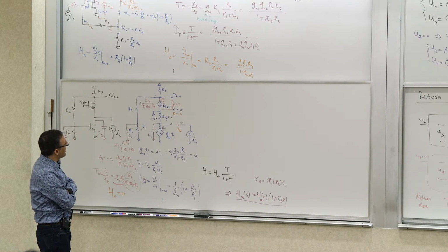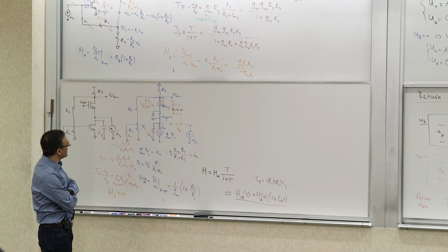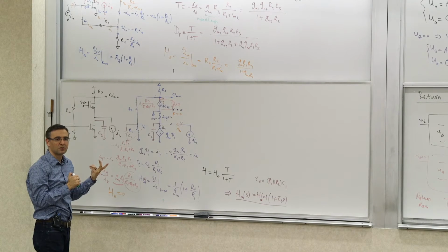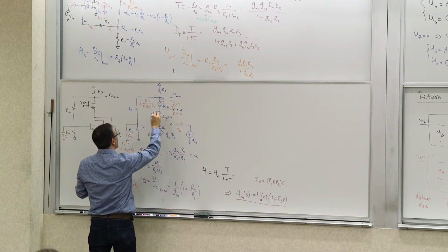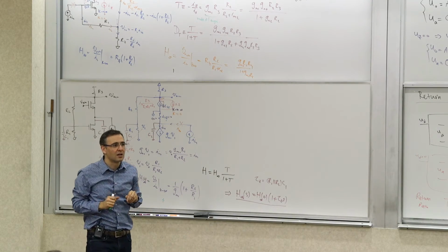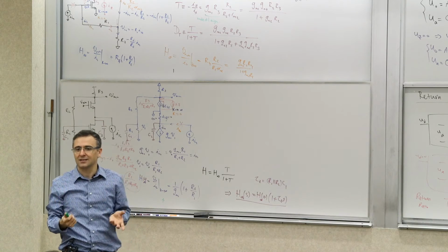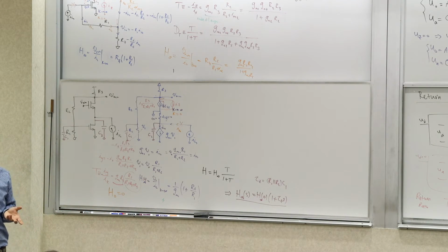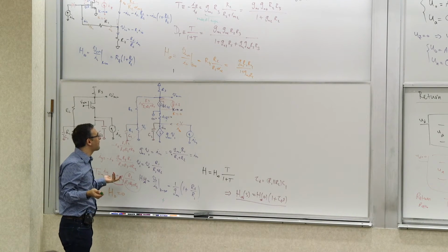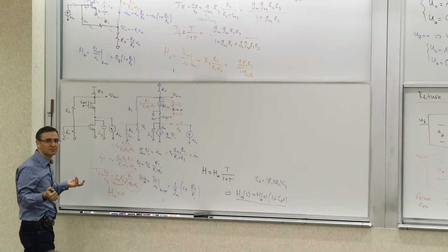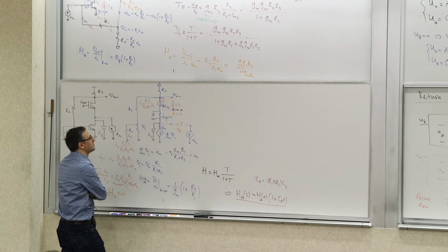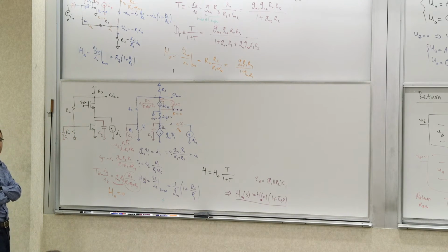Now, one thing that we can pay attention to when we are calculating the return ratio is how many poles and how many zeros from a return ratio calculation perspective we have. Meaning the transfer function from this Ix to this Iy. That's the return ratio, right? We have developed all these tools and techniques for calculating and determining this. What is it? How many poles do we have for that transfer function, and how many zeros? How many poles? Remember, for that calculation, this is not here. And k is 1 for that calculation.